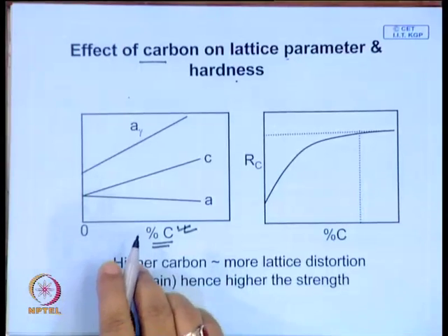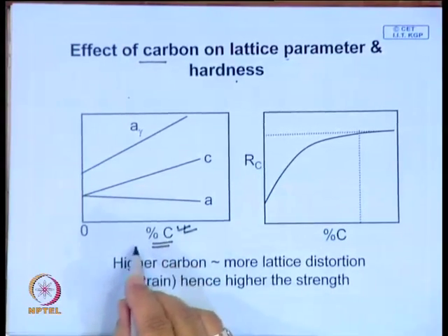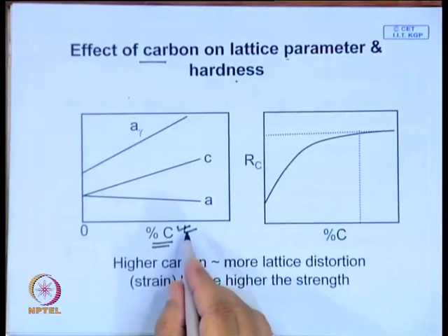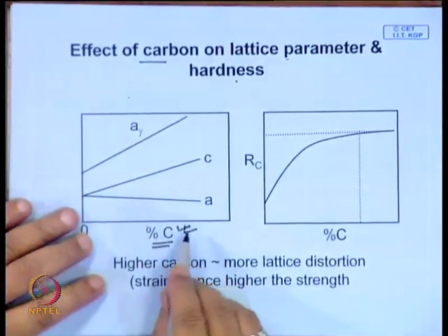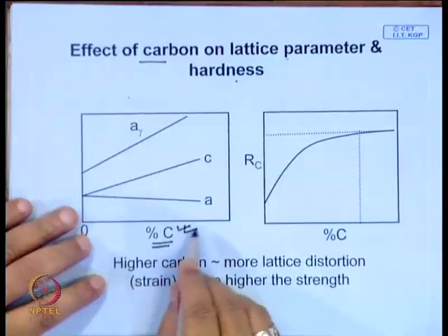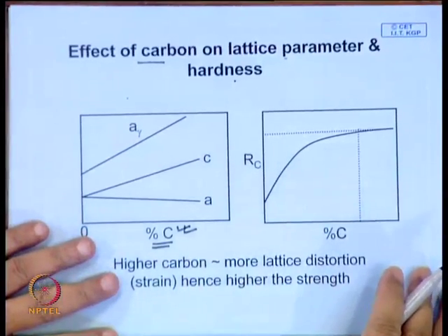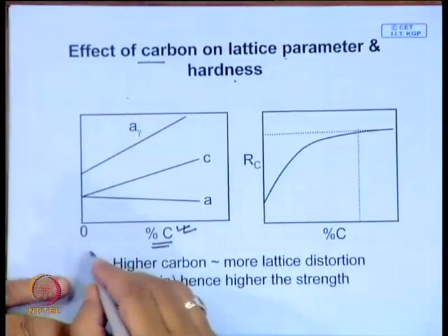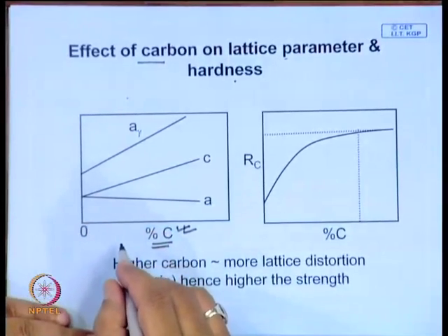So, martensite is a highly deformed structure, either plastically deformed or a twin structure, and which is submicroscopic. It is extremely difficult to see the fine structure of the plates or the laths. You can see it only under a transmission electron microscope, and the dimensions of the lath or plate, the interplate spacings, are of nanometer dimension.